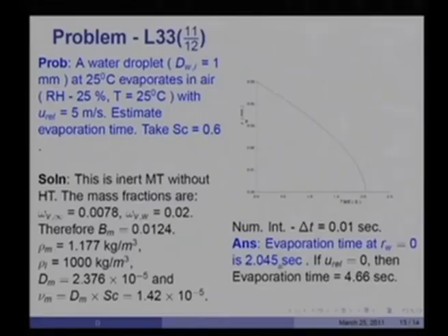So, clearly having a relative velocity between the gas and the droplet has reduced the evaporation time, and this is the principle that is used in cooling towers and in diesel engines for the purposes of reducing the size of the droplets in the case of cooling towers, and in diesel engines this is of great value because it enhances the rate of burning of the fuel, which incidentally also reduces the cutoff ratio of a diesel engine, which in turn improves the efficiency of the engine.